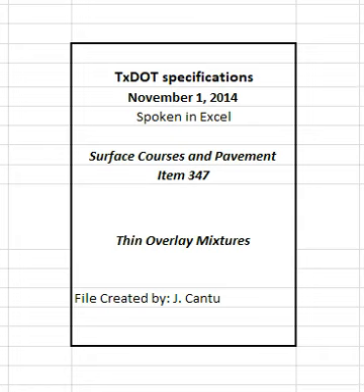4.9.2.2.2 Asphalt binder sampling. Obtain a 1 qt sample of the asphalt binder for each lot of mixture produced. Obtain the sample at approximately the same time the mixture random sample is obtained. Sample from a port located immediately upstream from the mixing drum or pug mill in accordance with Tex-500-C, Part 2. Label the can with the corresponding lot and sublot numbers, and deliver the sample to the engineer.